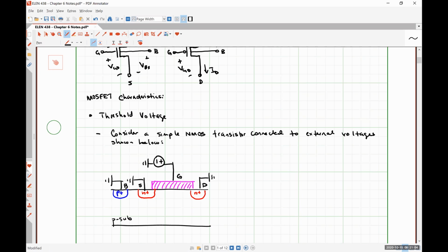You have to have the implant to avoid creating a Schottky diode, right? Or a metal semiconductor junction, which is a diode. And we don't want a one-way valve there, which is effectively all a diode is, right? So connecting to a highly conductive P+ region is effectively, you have metal, which has a lot of free charge carriers, connected to a P+ region, which has a lot of free charge carriers. So there's an easy conductive path, and then a P+ junction connected to the P substrate is a semiconductor to semiconductor junction. So it doesn't form a diode either.